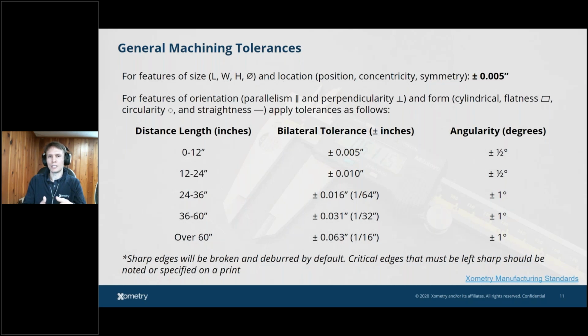These are industry acceptable tolerances. These are ones that would be accepted across multiple customer bases, including some of our major customers: BMW, NASA, GE, Bosch, Dell, and they're accepted by manufacturers alike. So these are relatively agreed upon. For the most part, with CNC, the general guideline is plus or minus 5 thousandths of an inch. So that's about the thickness of a sheet of paper. So again, if I upload a file, just the CAD, and press go, that's going to be my general assumption.